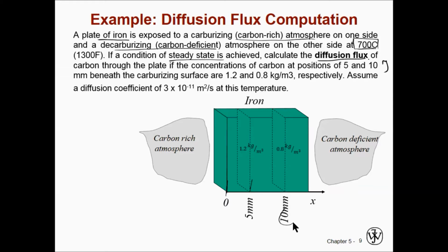At 10 millimeters into the material, carbon concentration is this. The diffusion coefficient is given. If it is not, we can read it from the table. We will see it later. So we have to calculate diffusion flux.